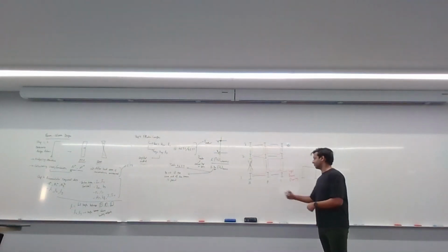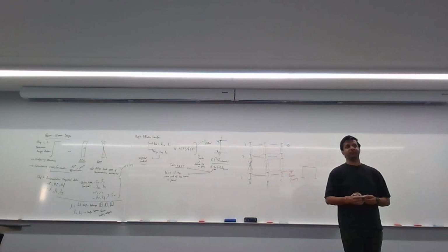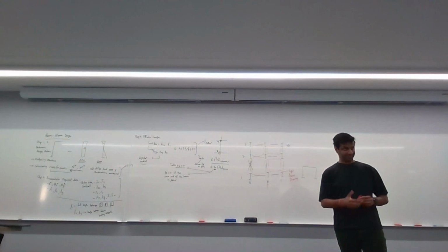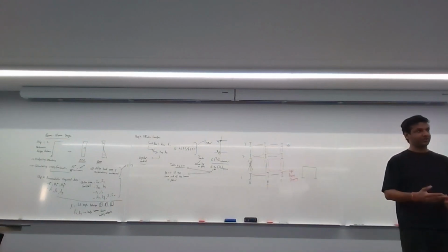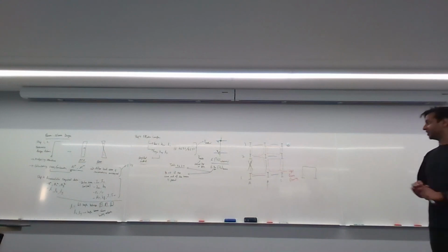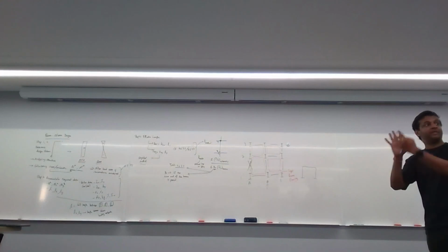So basically what I'm asking you is, if you apply a load here, is frame B going to operate like a braced frame or a sway frame? Why? Just like a wall. If you put the force here, it will be defended by the wall, so it's braced. Okay, so you're saying because A is braced, B is also braced.